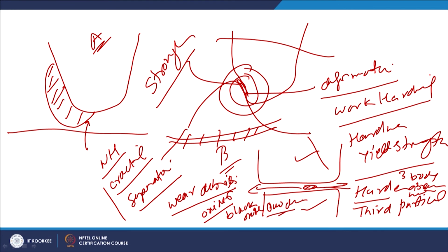So, this black oxide powder, if characterized using the XRD technique, most of the time turns out to be the oxides of the various constituents present in a given metal. So, this is how the separation of material during adhesive wear takes place. Now, there will be various factors affecting such bond formation, like the loading, the yield strength of the material, and the speed or the time they have to form such bonds. About those factors we will be talking in the next presentation.